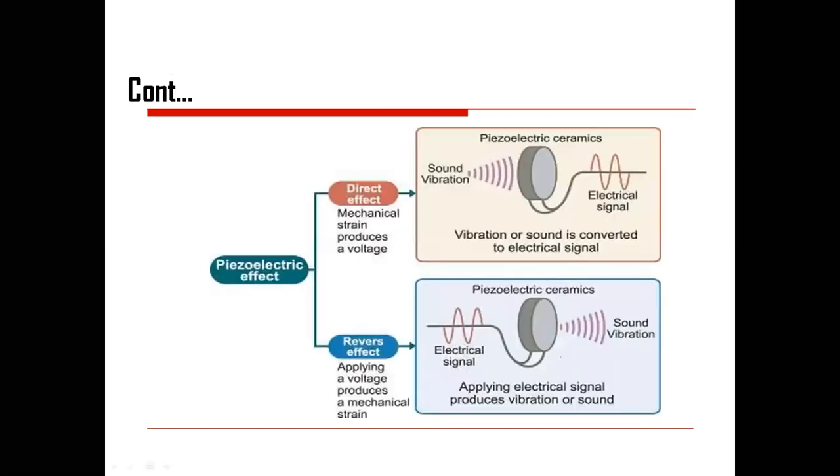So what is the concept for the displacement measurement? Both the inverse and non-inverse concepts are provided here. This is the piezoelectric effect, shown in blue. Then the direct effect and reverse effect are also provided: when mechanical strain is applied, it produces voltage, or a sound vibration striking the piezoelectric ceramic, so an electric signal is generated.